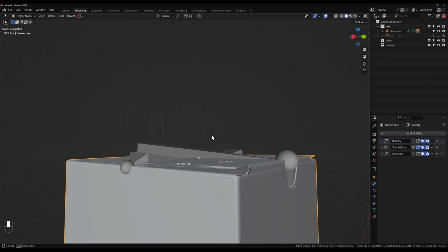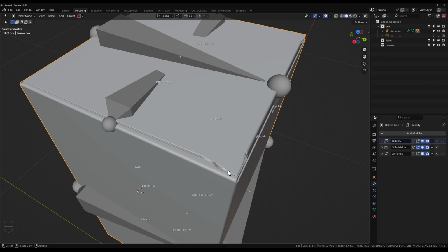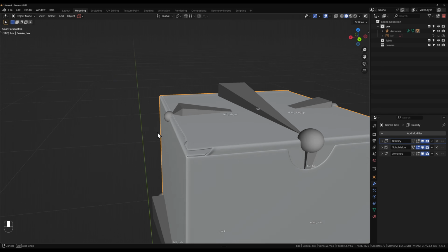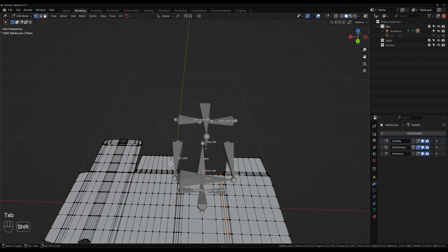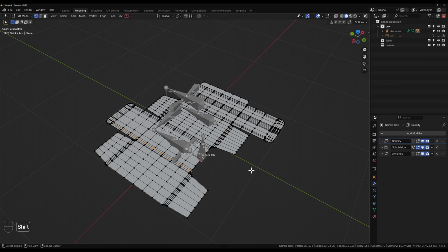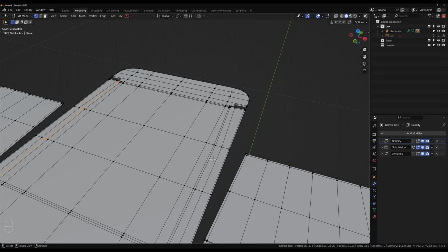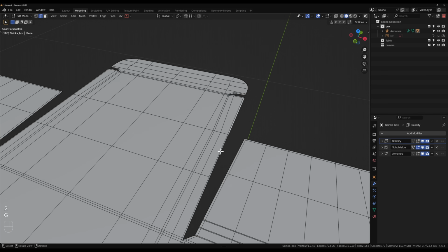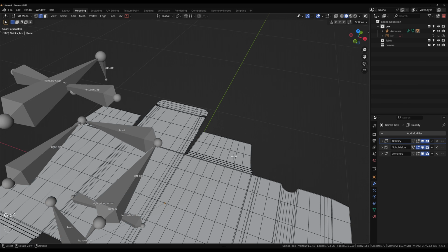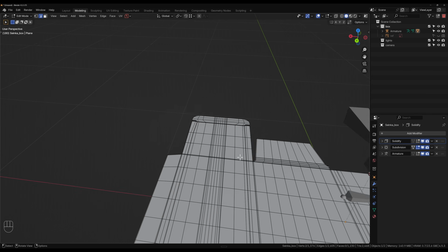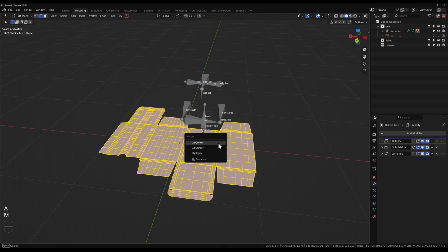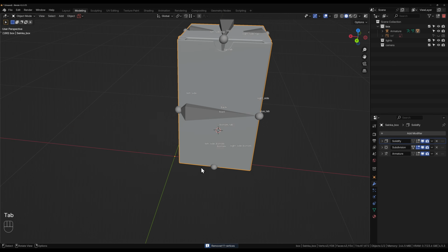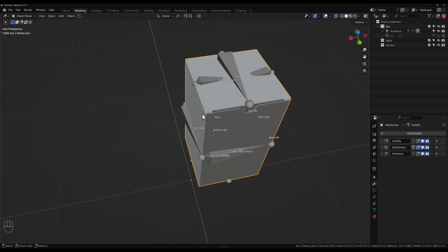Yeah, you'd need to fix up the topology on this to make it work. Which that actually looks like it's just on one side. I think it's here. I think there's a duplicate edge somewhere. There. To see. Oh no. Where are you? You over here. Let's just select all of this. A, press M, merge by distance. That didn't get rid of it. It's just this edge here.